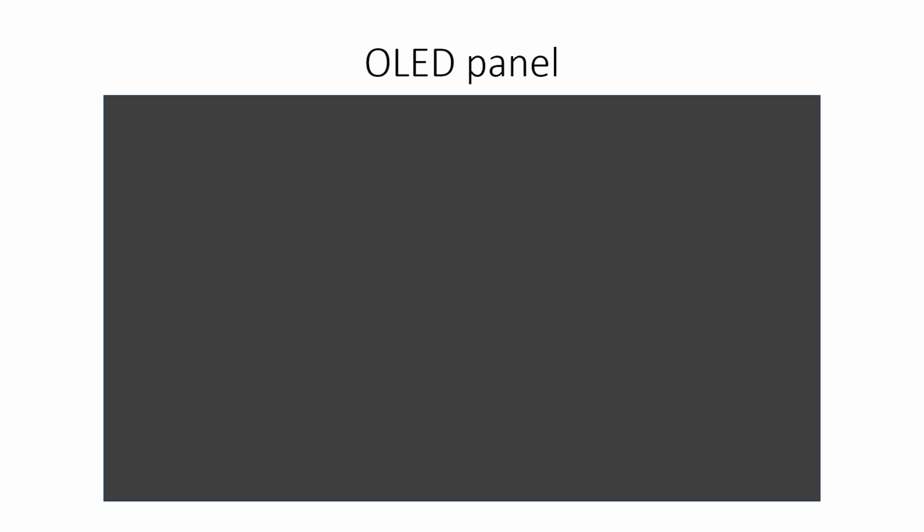Each LED can be individually addressed and the brightness of each colour varied as the current through the LED is varied. This then enables a raster scan to be produced to build up the picture in the same way as was described in the previous videos.